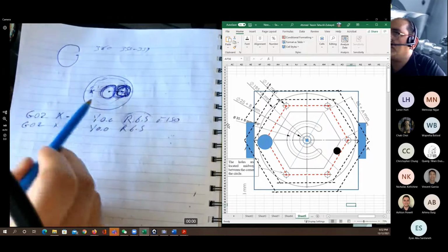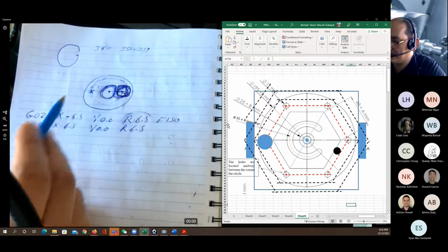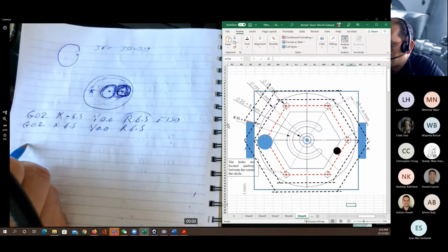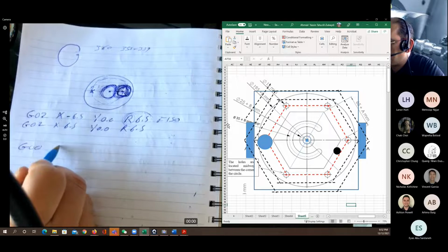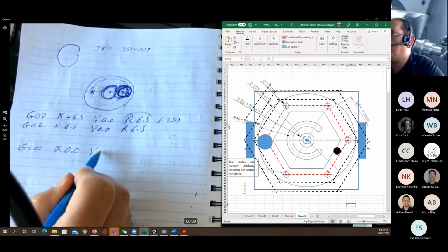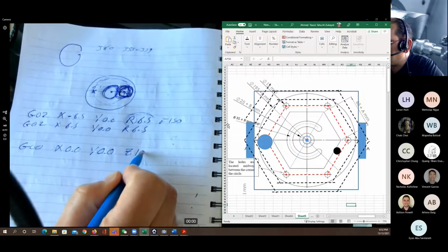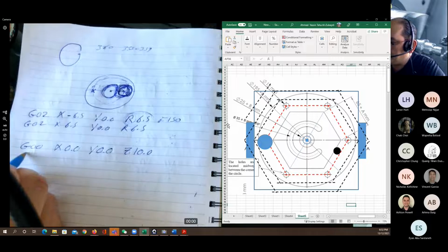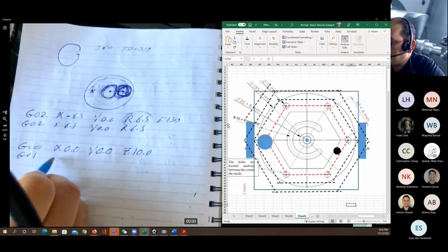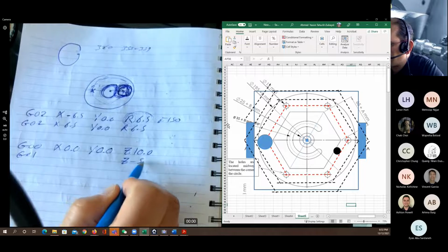So we can finish that and do it as one cut. I'll write down the code, coming to the center, going to the side, and cut, clean the pocket. So G00, X equal to 0, Y is equal to 0, the Z is equal to 10. G01, X and Y not changing, Z is equal to, let's say, minus 5.